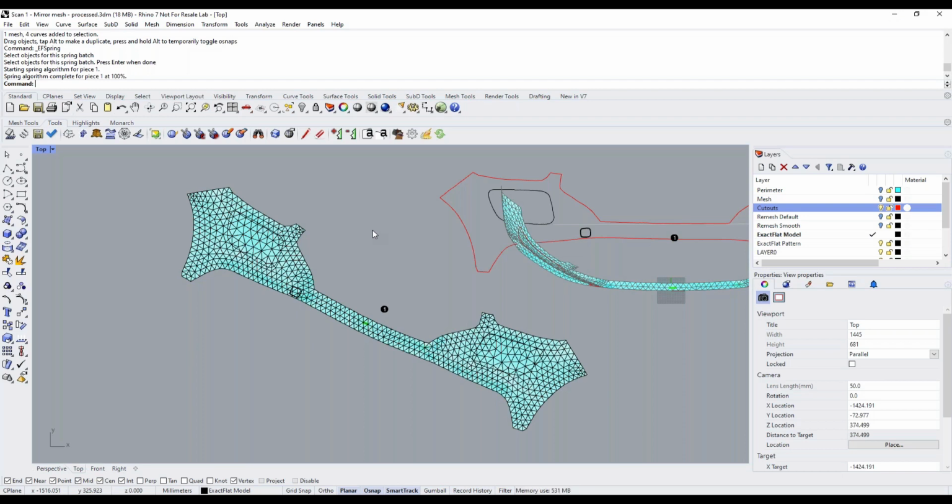My understanding of the VX Elements flatteners is that they are brand new, and primarily for more developable surfaces. These are surfaces that only have a curvature in one direction. So that is a point to take into consideration here. You'll need to make the right assessment for yourself. If you're doing cylindrical or non-developable surfaces, you'll have to test it and make sure.